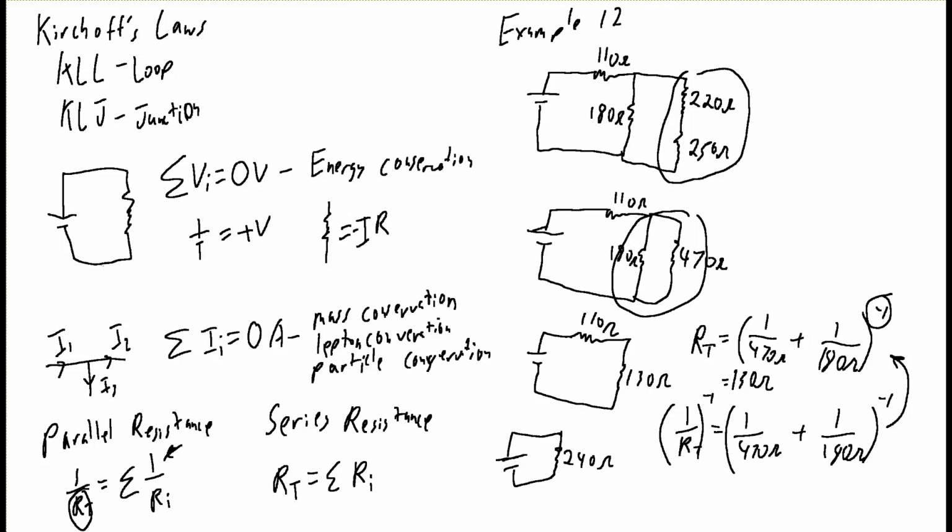There are 220s, right? Yeah, there's 220. There's 250. Nope, no 250s either. But there's a 180. So two of those resistors are common and two of them are not. Anyhow. So I guess I won't build that. Anyhow. So that's example 12 and how we apply the parallel and series resistances to that stuff.